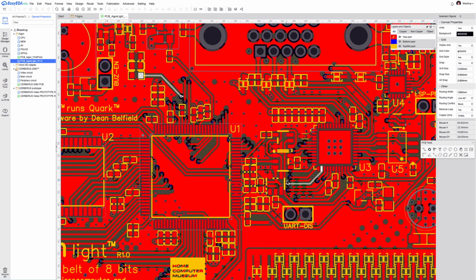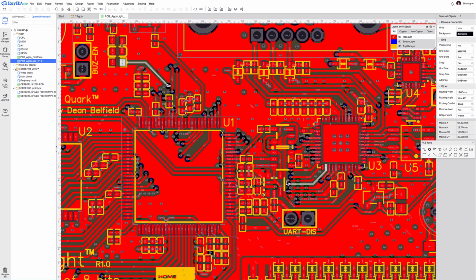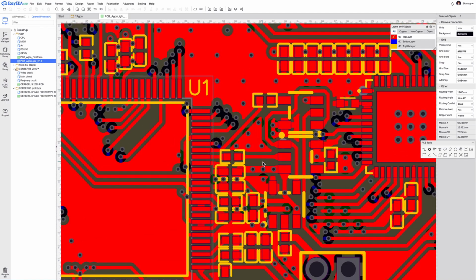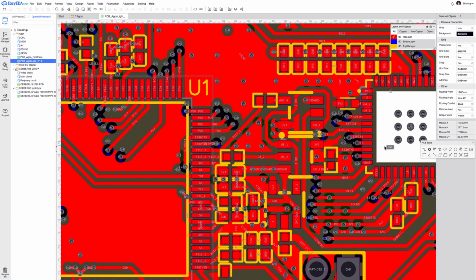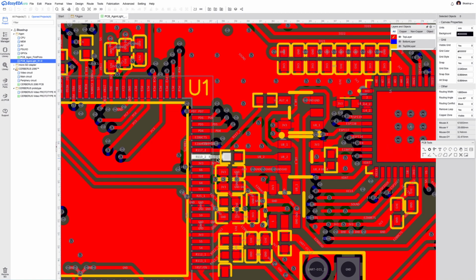Now, I think I spoke about most of the relevant things, but when it comes to the floor planning, I tried to keep this line here. This is the transmitter, the UART transmitter of the CPU that sends display list commands to the ESP32, which plays the role of graphics processor or video display processor. This is the critical line that needs to be protected and be at a very high speed. So you see it's a very short line here.